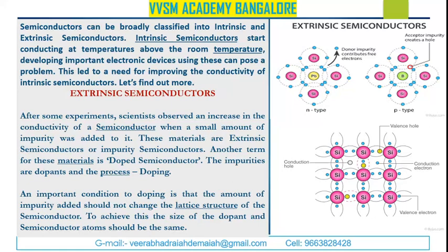After some experiments, it was found that when a small amount of impurity is added to the semiconductor, that is nothing but doping. In the process of doping, the impurities are called dopants. An important condition for doping is that the amount of impurity added should not change the lattice structure of the semiconductor. To achieve this, the size of the dopant and the semiconductor's atom should be the same.